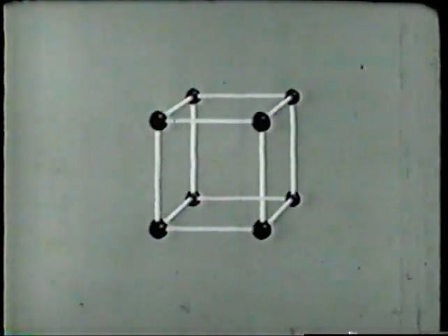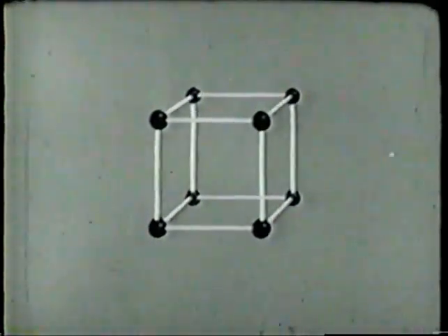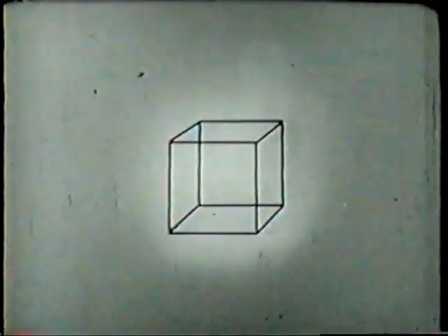Microscopic study of a cross-section of an aluminum alloy specimen reveals a network formed by the boundaries between grains of the metal. Each grain is an accumulation of individual crystals or unit cells. The single crystal or unit cell is conceived to be cube-shaped with atoms of the metal arranged in regular order, one at each corner and one in the center of each face of the cube. These unit cells combine to form what is known as a space lattice.